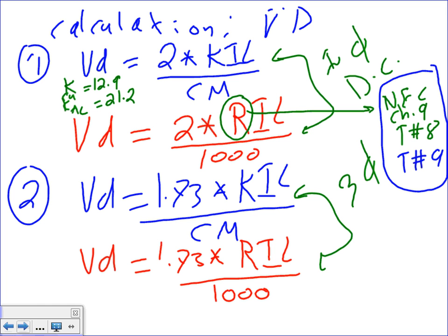What's the 1.73 and why do we have it? 3-phase, duh, Chad. What's the K? The constant, material dependent. I is current, L is length, and circular mill is circular mill. R is the same R, and it changes into impedance later on. Any question, guys? Any question about the criteria? Have we established the criteria?